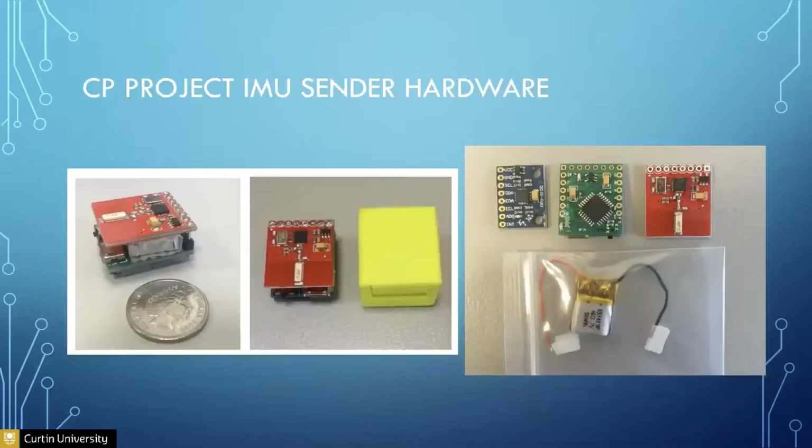Another example, something that I'm working on, is a modified Arduino Pro Mini, that green board, and again an MPU 9150, the older generation of the 9250s, and an RF transmitter. I'm using these to capture the movement, specifically the wrist movement of children with cerebral palsy. I have two of these sensors connected, one to the back of the hand and one slightly above the rest. Later on, I'm going to use machine learning to capture this movement and distinguish, given a random captured sample, where it falls.